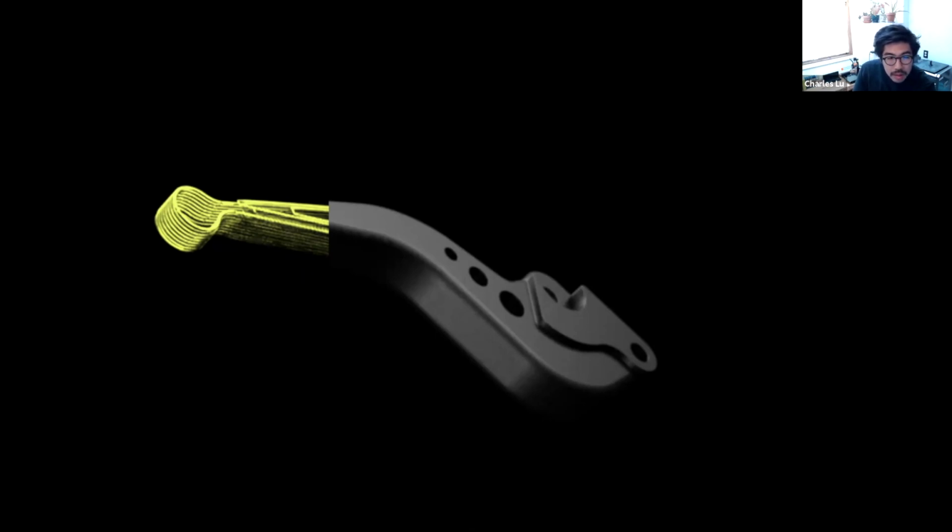Porosity, could they be used for applications that require waterproof sealings? I would say that you would need to seal them because they're FDM. You are printing in discrete layers and discrete paths. In order to get that to seal, you could use a sort of vacuum impregnation. That might be good, or you could use a spray coat if it's not so critical. Spray coat seems to work pretty well.